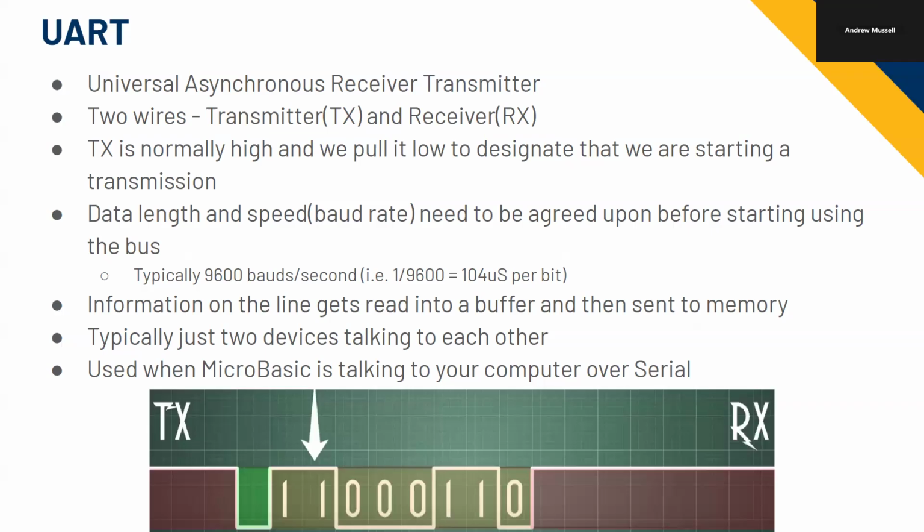Once you get past 115200, there are some more things you have to think about for higher speed communication, where there are some extra serial pins that you'll need to make sure you meet timing.